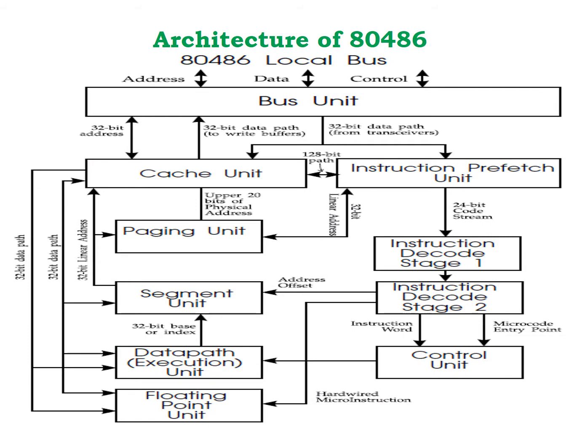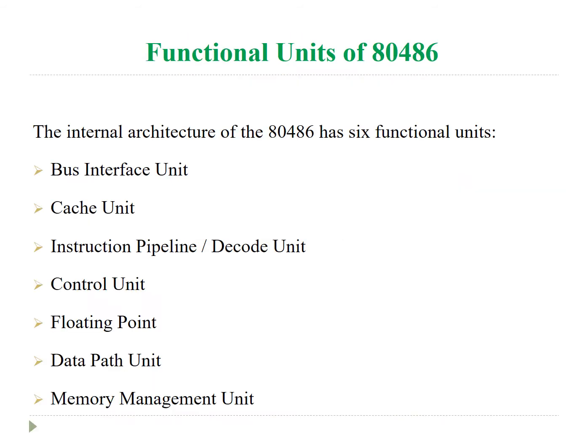As the picture illustrates, the 486 microprocessor consists of a number of system elements incorporated on one chip. The elements incorporated on the 486 are an enhanced 386, floating point processor 387, cache memory controller and 8 kilobytes of cache memory and additional new features. The 486 consists of the following 6 functional units.